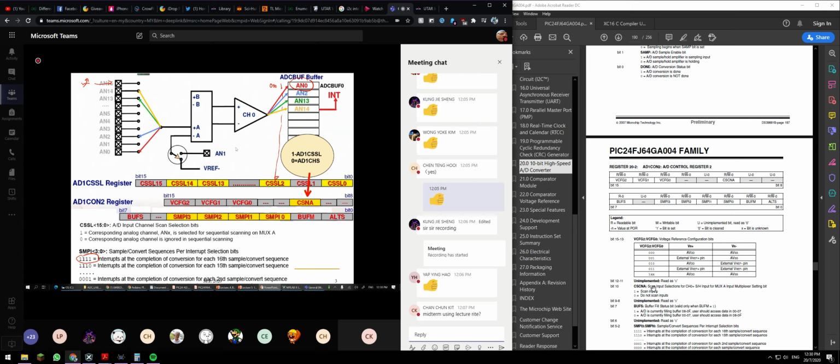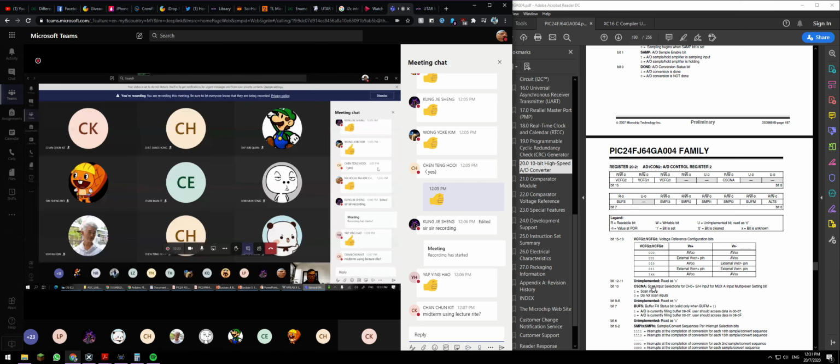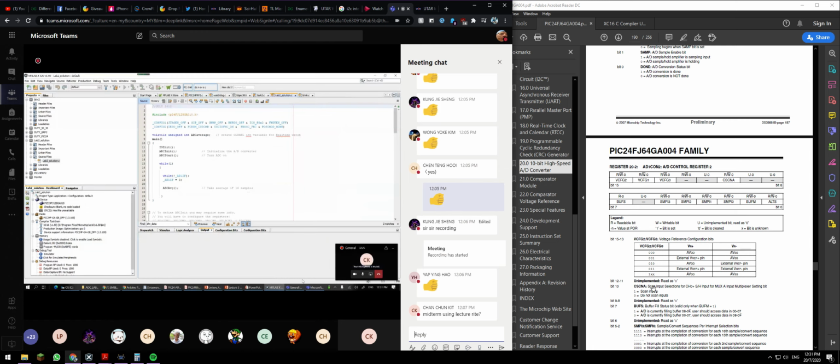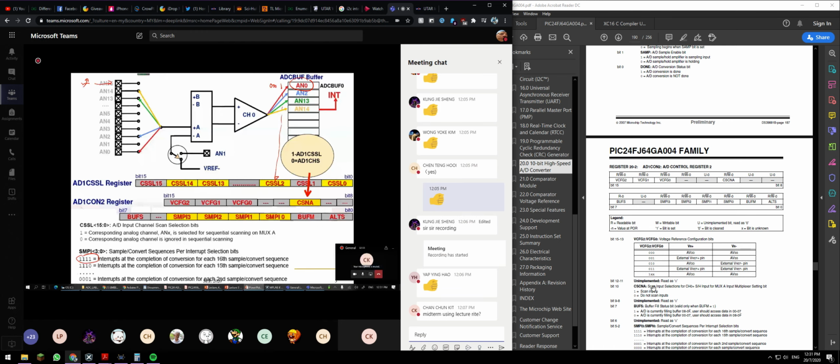Okay, so let's move on. Class, even though you're using MPLAB X, you can also perform debugging by selecting any input value. In our assignment, we are using a variable resistor, so different values will come in, correct? You can assume any value stored in the buffer so that we can see whether the output is correct or not, because we are not able to touch the input.